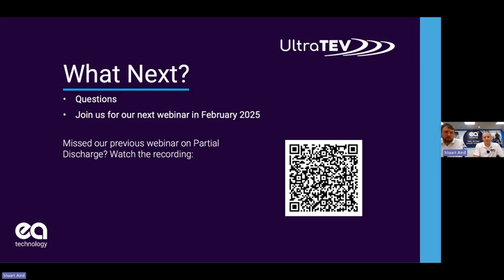Yeah. Okay, so there is, and thank you for the question. We do provide permanent monitoring systems that can be either permanent or semi-permanent. If you know you've got an issue and you want to trend or manage that gear, then we can install it temporarily. It just magnetically clamps to the outside of the switchgear, so it can be done with the system fully live, and we'll cover your cables, your switchgear and your transformers. Equally, that can be a permanent monitoring system with all the data back to the cloud, and we can manage that service for you. So definitely something that can be offered. Generally, compared to a handheld device, it's got a slightly higher cost, and you'll be using that on your more critical assets. Thank you.